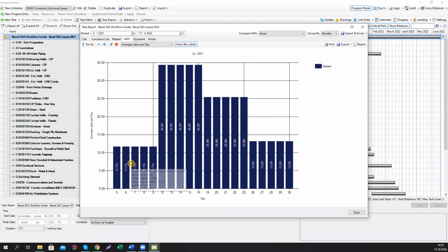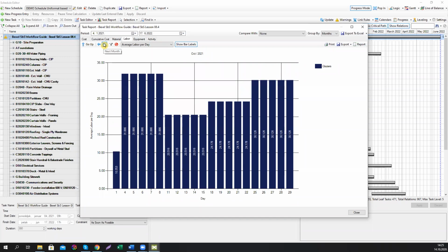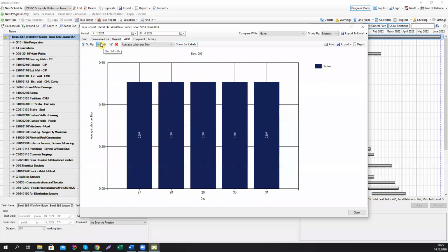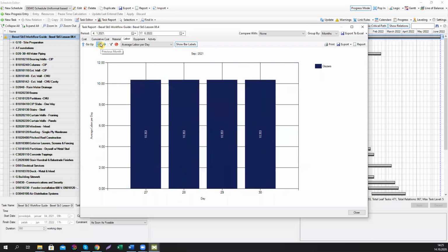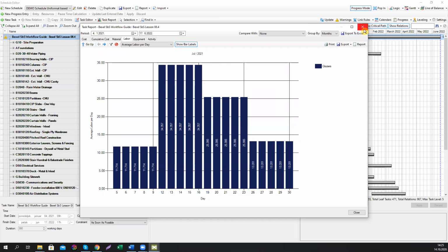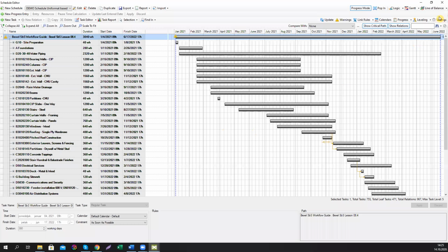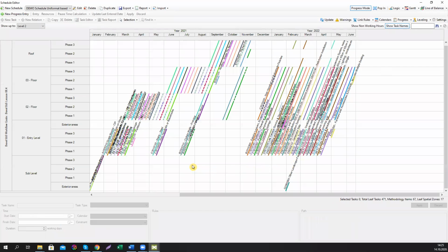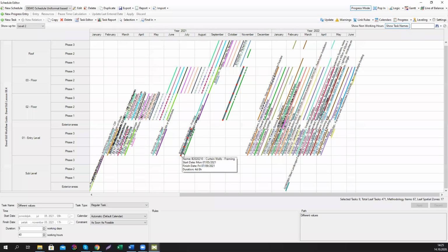So you see, for 1 week you have 12 people on site working on these tasks, then you have 35 people, then the next week 25, then again 13. There's no way you can sustain such a huge variation in the workforce on your construction site. So this schedule is unrealistic when it comes to this activity. These resources are mainly connected to curtain wall execution.